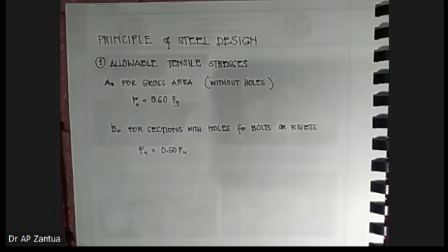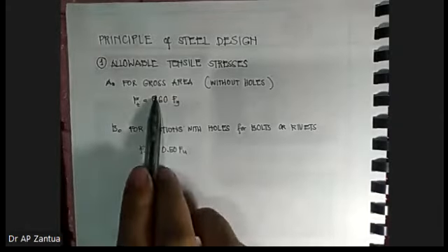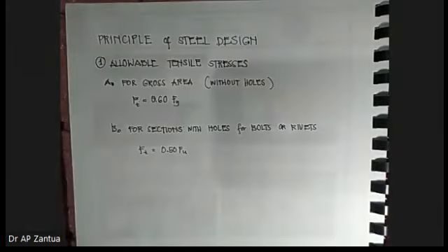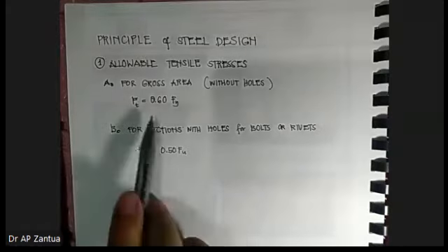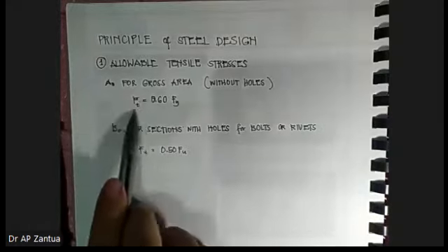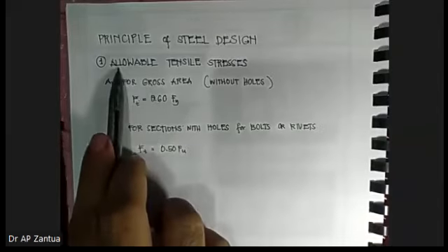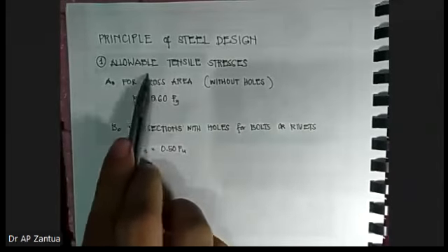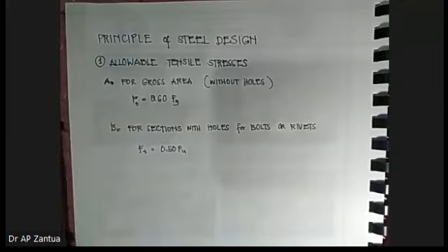It is about 60% to 70%, so it is very near here. That's why the possibility of failure at 600, 550, even 500 degrees Celsius is higher. The risk of failure at that temperature is great because it is very near our target allowable, meaning the maximum allowed load.